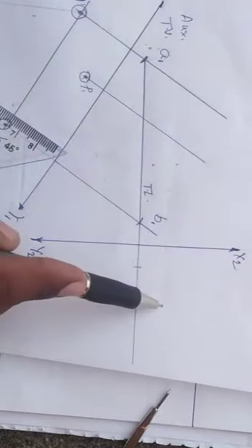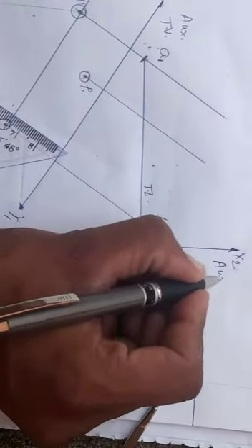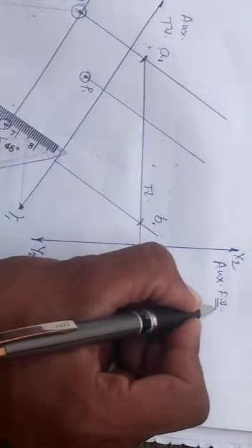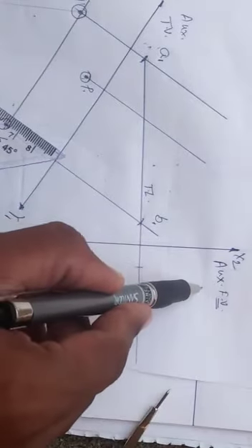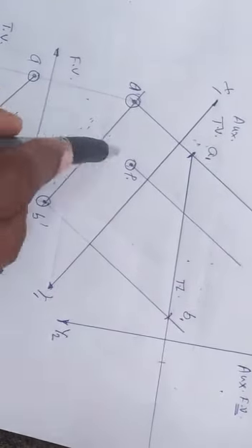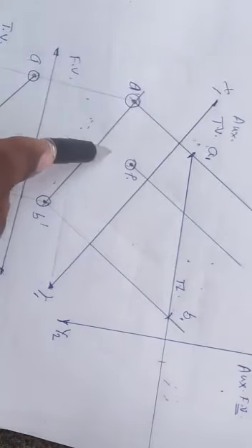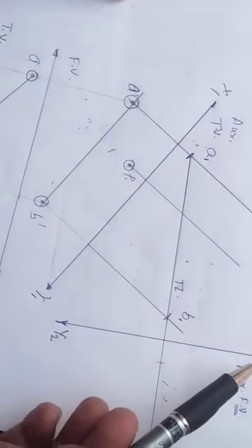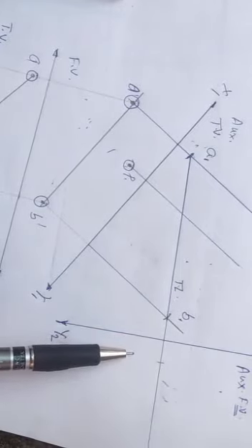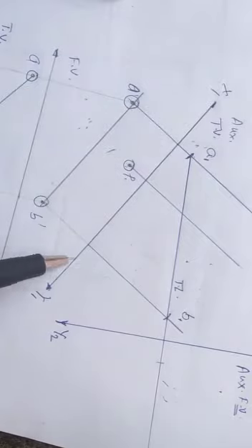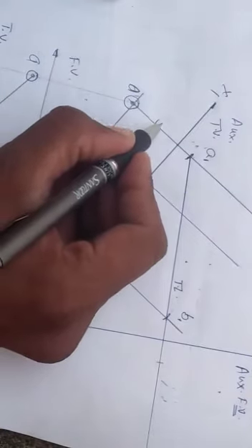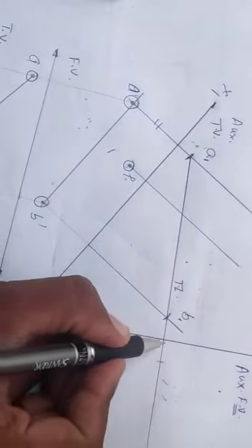After this auxiliary top view, here we are getting the auxiliary front view. As we are going to locate the front view, we need to measure the distances from the front view. So here it is the front view. In this view, we are going to transfer the distances from that view. Now we have x2 y2. So measure the distances from the previous xy, which is x1 y1, and plot here.